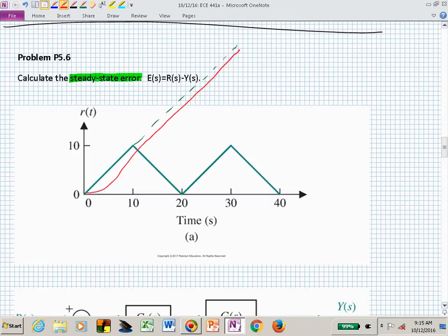And hopefully, if this was drawn accurately, what's happening at 9 is the same as what's happening at 12, at 30, if you pretended that it just went on forever. That's why you can get away with using the final value theorem. You're going, well, the final value theorem is what happens at infinity. Well, now you have to interpret what is infinity. And it's when you're beyond that settling time.